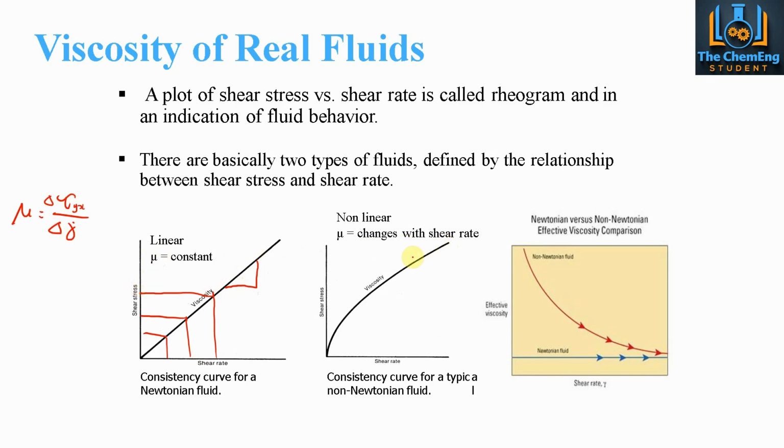So we can look at this graph and deduce what type of fluid we actually have, because say from this point to that point we have a specific gradient, so it's quite steep. Whereas if we come up here, then the gradient is much less. That indicates that we have a shear thinning fluid, because the viscosity is getting less and less as the shear rate increases.